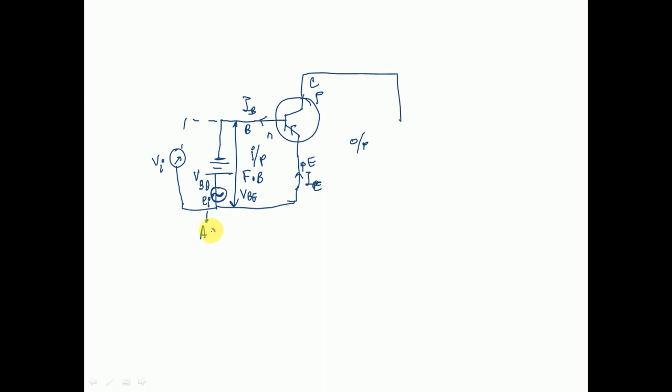So you can write down: AC signal with lower amplitude as an input. It has been fed into the input circuit which is forward biased. This is a base biased PNP transistor in the common emitter configuration. Why am I saying common emitter? Because this is the emitter, and I am connecting it to the output circuit as well.